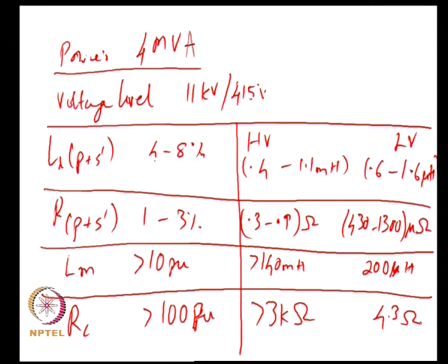Whereas if it is 10 per unit, it means that the no load current is 10% of your rating, which might be reasonable. So, again just looking at these components, for example, your core loss resistance, if it is 10 per unit, it means that immediately the core losses are 10% of your rating, so your no load losses would be 10%, which might be immediately considered as unacceptable.